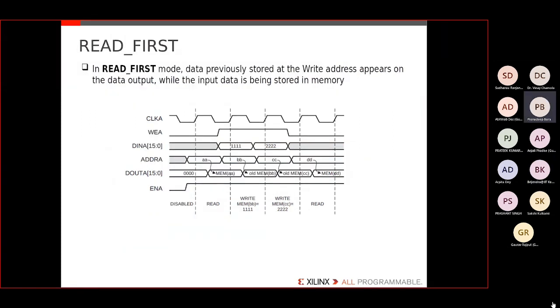Similarly, you can see read first. Read first is like the generic one. I don't need the data to be transparent. That means I don't need the data to come at that clock cycle only. I can wait for one clock cycle, so I can use read first mode. The previously stored data will come out, and in the next clock cycle the new data will come here. So this is read first.